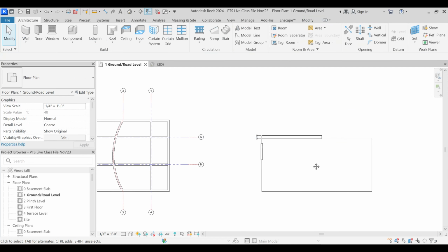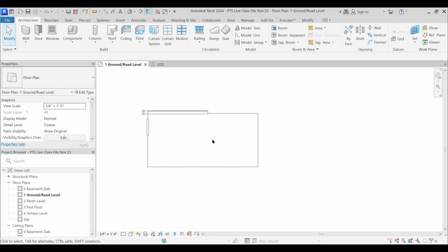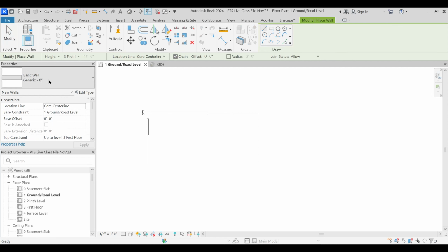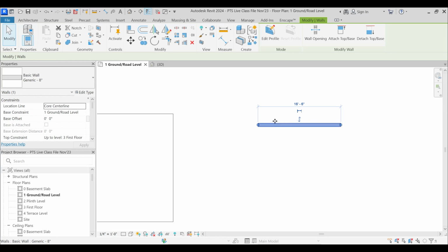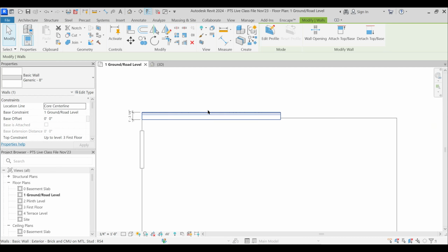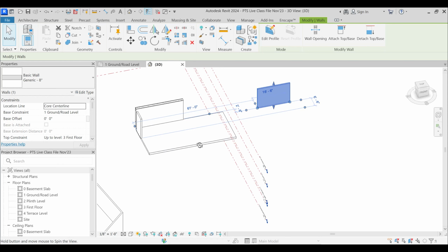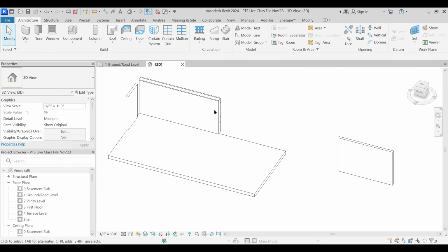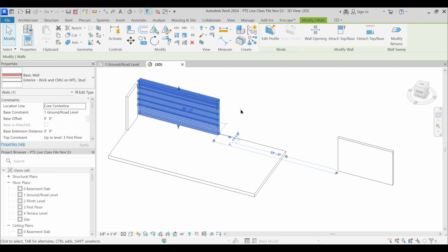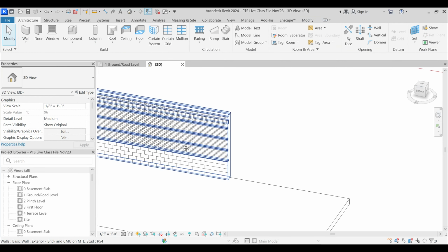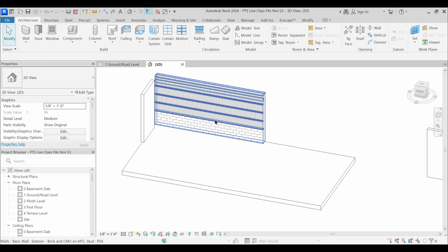And for that, we will create one wall from the start, which is a simple generic 8-inch wall. Fine, a simple generic 8-inch wall. We will start with this particular wall, and we will end up creating this, and after creating this, we will move away from this. See, while in the 3D environment, if I click this wall and if I want to flip the direction, flip between exterior and interior, I will just press space. That will flip. And you see that in 3D also, this wall is slightly different than this. Slightly no, it is very much different.